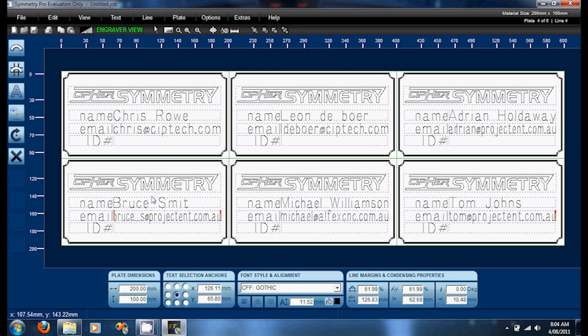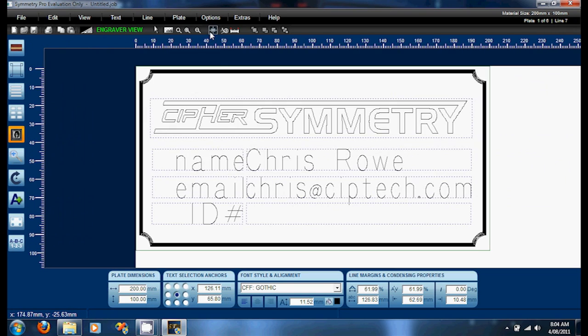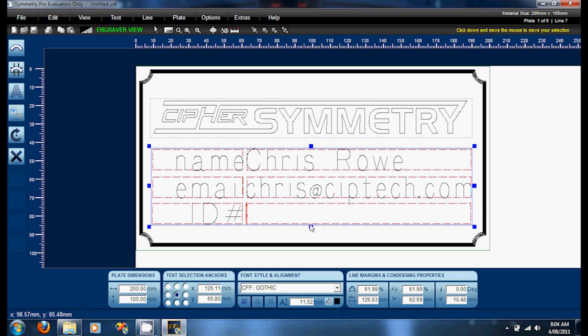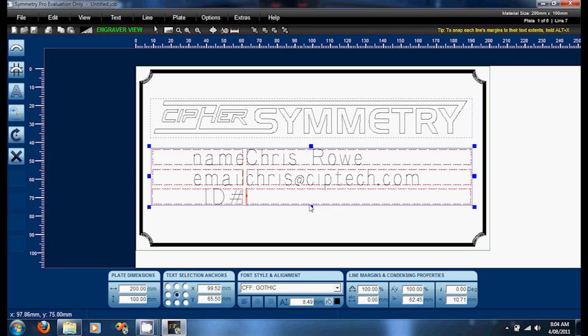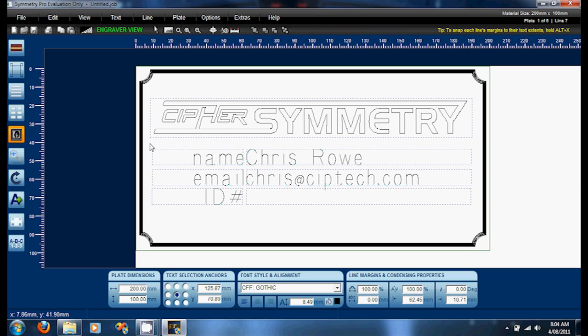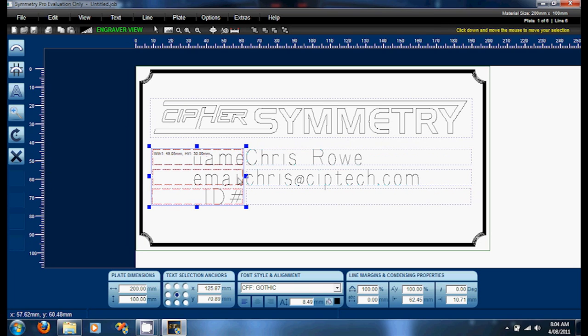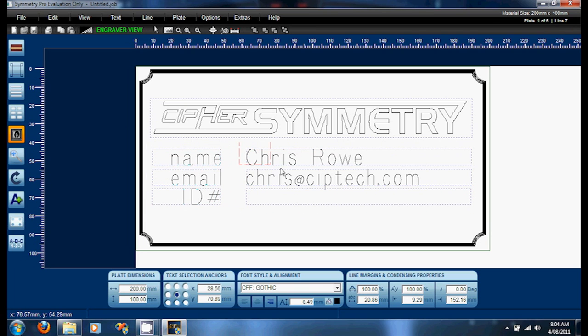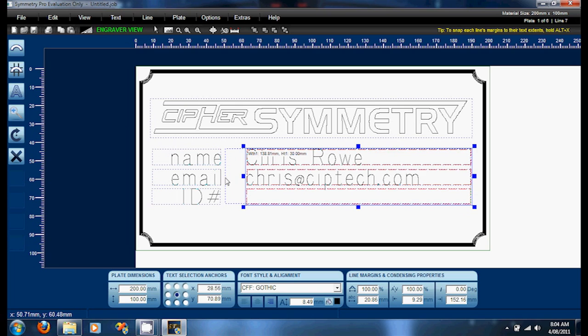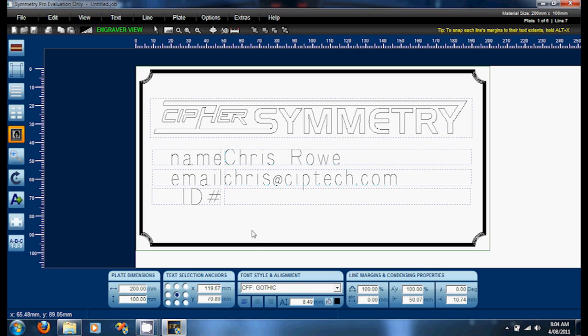Now you can see here there's a few email addresses in particular which are a little bit too condensed up, so I don't really like that. I want to make the layout look like it all fits nicely. So we'll just click on plate 1, and I'm just going to zoom to that plate for a second. What I'm going to do, I'm going to adjust plate 1 so it looks right. So to do that, what I'll probably just need to do is reduce the height of the characters and also give them just that little bit more space as well. Alright, so that's looking a lot better.